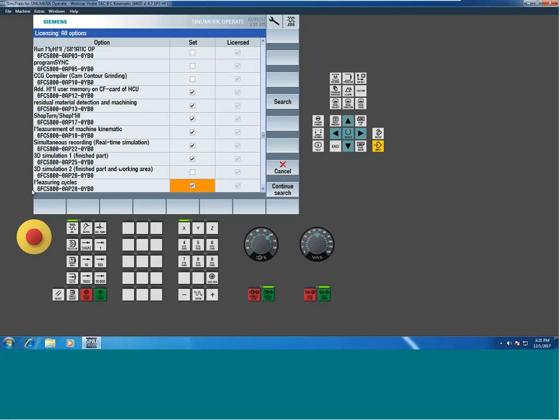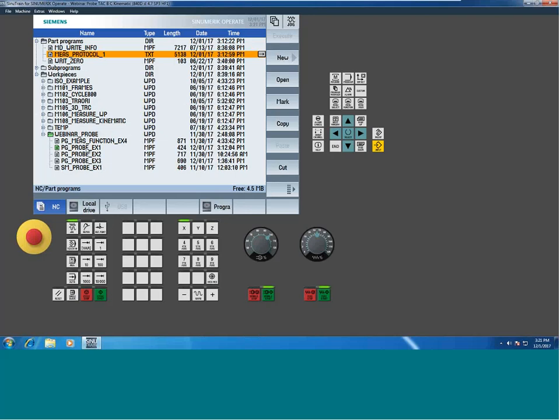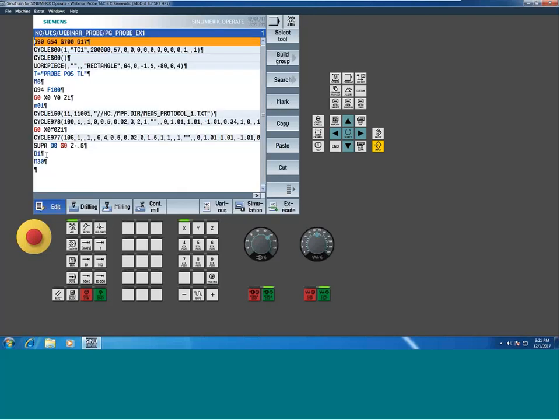But what you can do is create conditionals. So then when you drop down to the area in that main program, then it's just like calling up any other subprogram. So you're just going to then literally call the other program. And calling up subprograms in the Siemens control is pretty easy. If you are inside of a program, just go into any program, and let's say right here, I want to call up a sub. A couple different ways to do it.